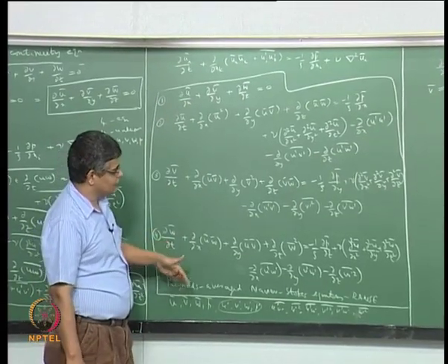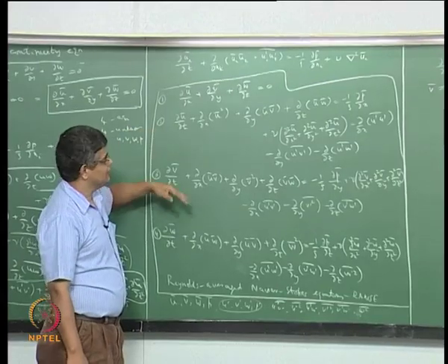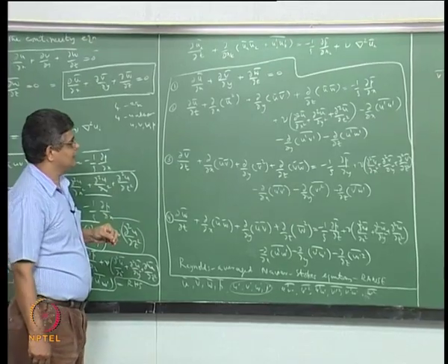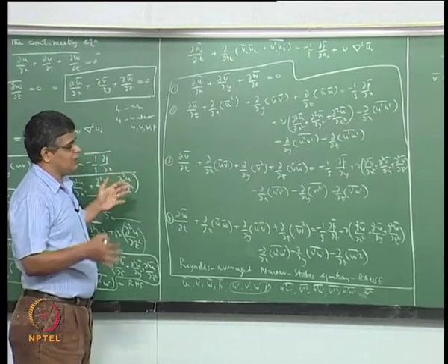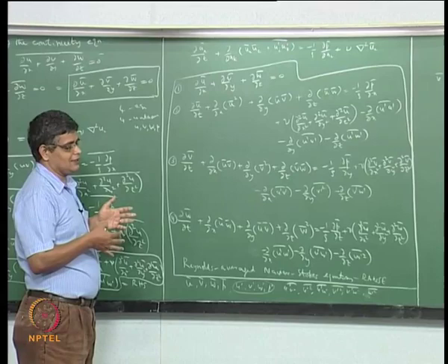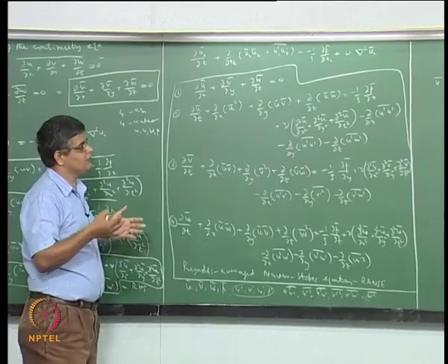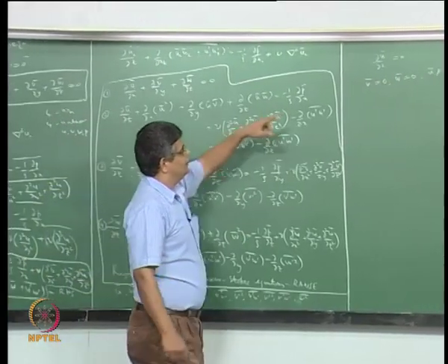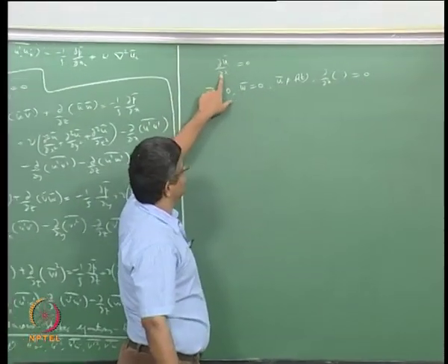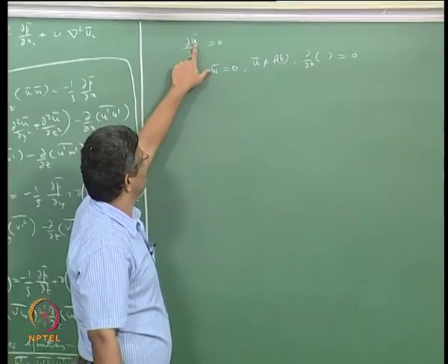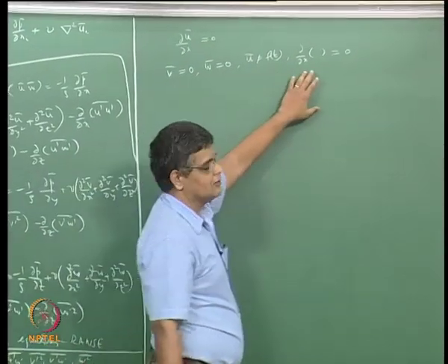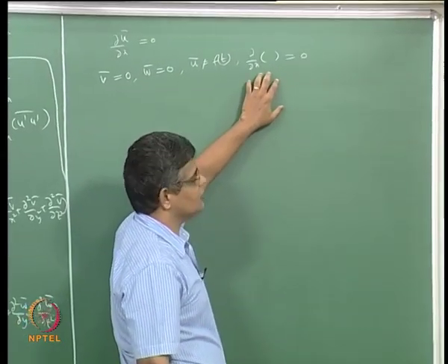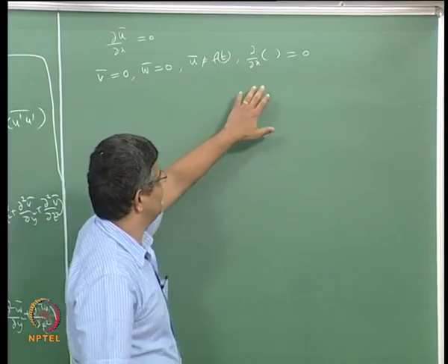We have said that even though the flow is turbulent and therefore 3-dimensional and transient, for the case where one can assume steadiness and fully developed flow condition in the turbulent flow sense, that is, the variation of a time average quantity in the x direction being equal to 0 is the fully developed condition in the turbulent flow sense.